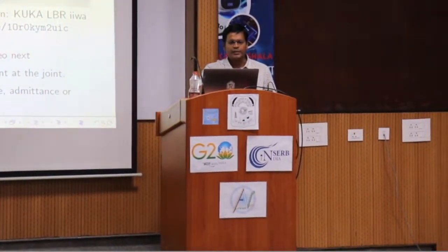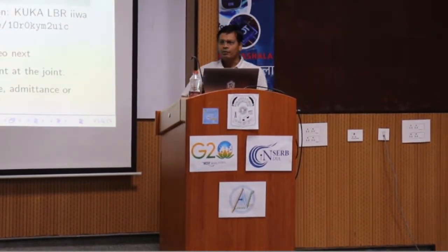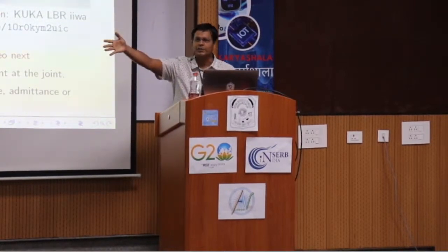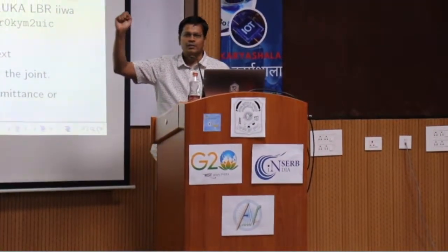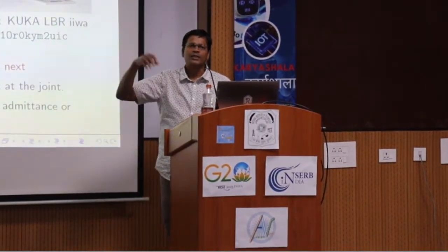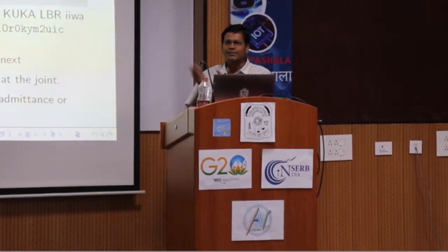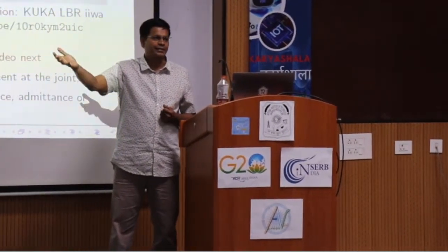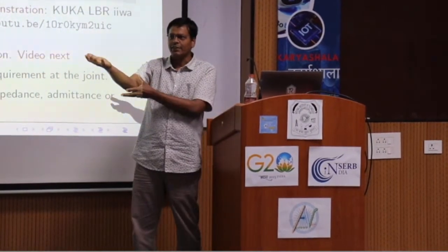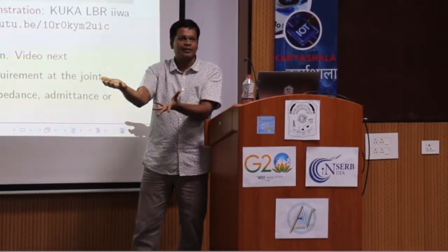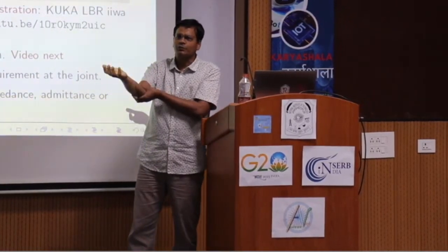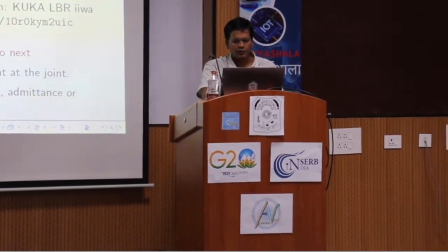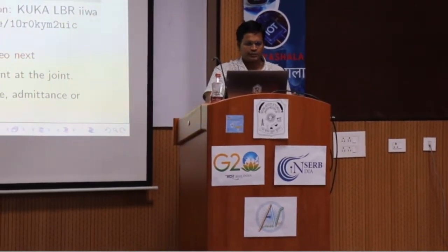And it is implemented using various force control algorithms. You have algorithms that calculate exactly how much torque is going to come at this location due to gravity. You feed your motors with exactly that amount of torque because it has joint angle sensors at each joint. So it knows its state. The robot knows its state at every point, it knows how much gravity force is going to come, exactly that amount of torque is fed and it is compensated, right? Okay.